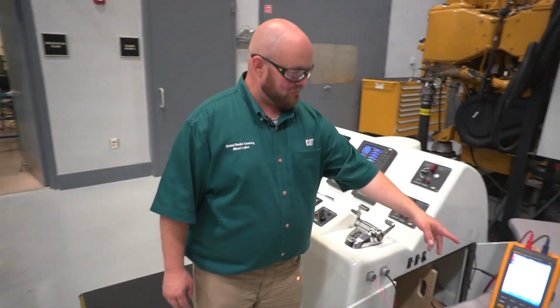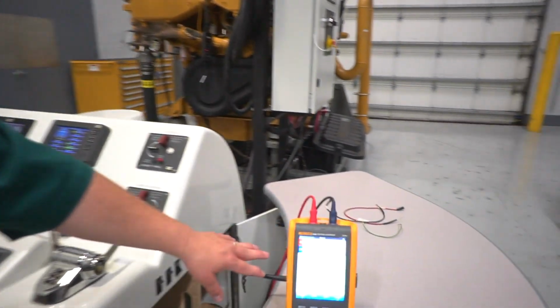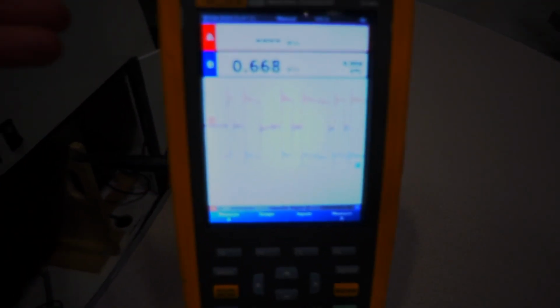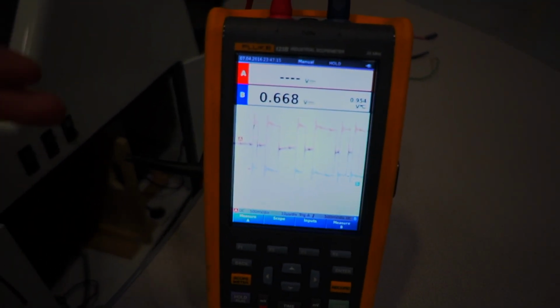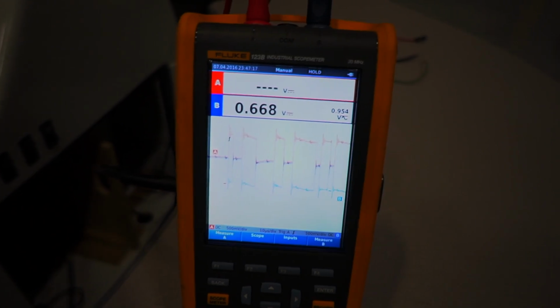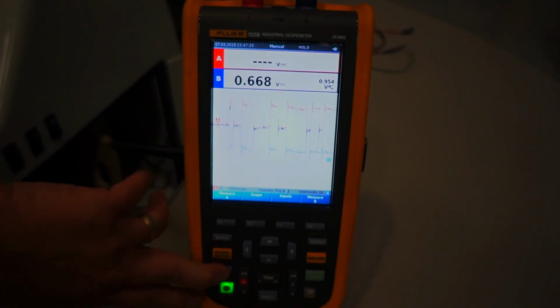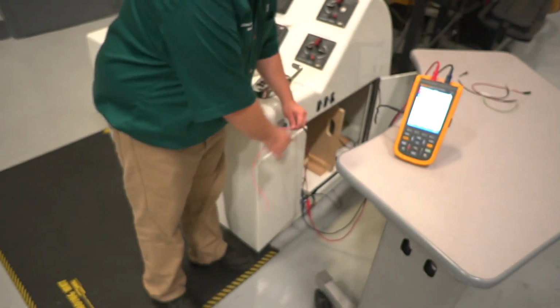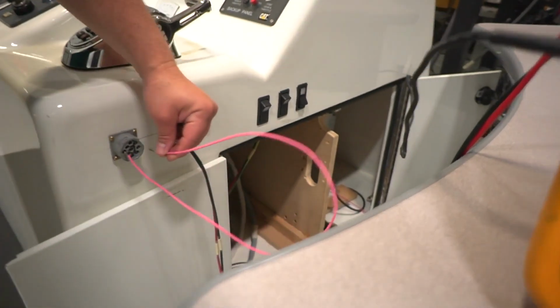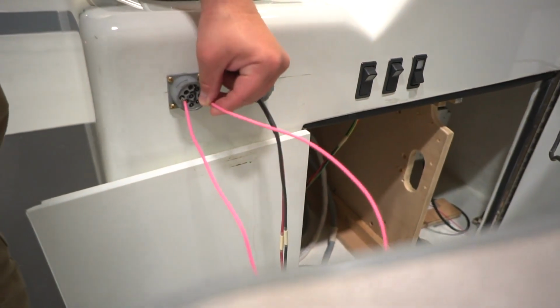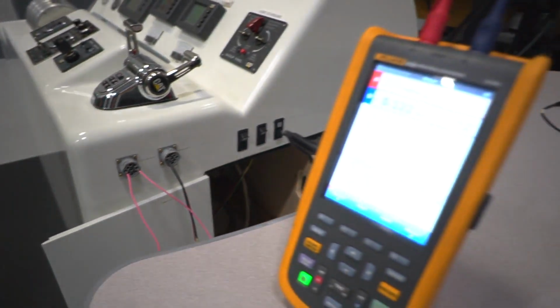Let's make everybody happy again. So that was shorting out, and you can see our signal is back to looking pretty normal. We'll pause it here for a second. We can see the boxes here, right, where the two voltages go together, where they separate apart. This all looks pretty good. And so we'll go ahead and run again. Now let's see what happens if we ground out our CAN negative, which is pin F. So we'll short it out.